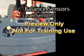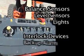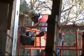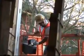Check balance sensors, level sensors, controls, lights, interlock devices, backup alarm, and intercom for proper operation. The emergency descent system should be checked by raising the platform a couple of feet and then turning the lift off and using the auxiliary power to lower the lift.